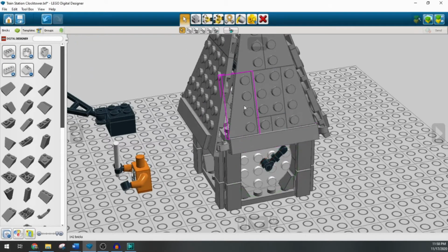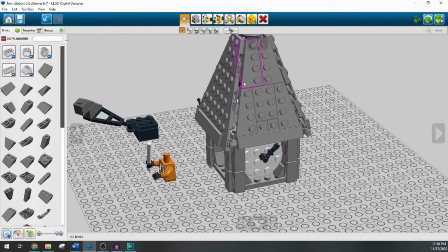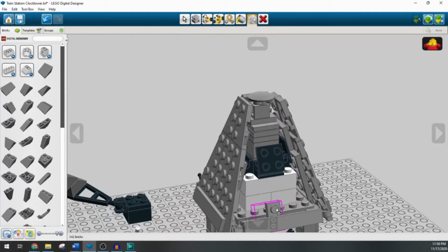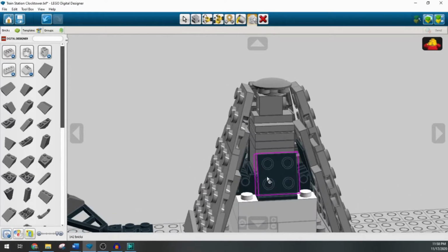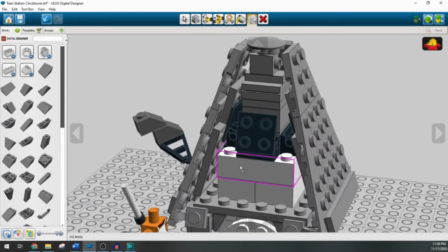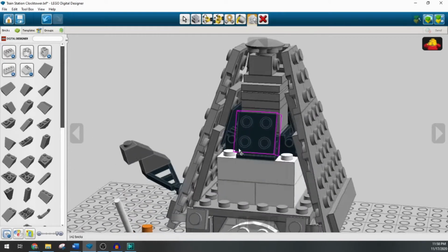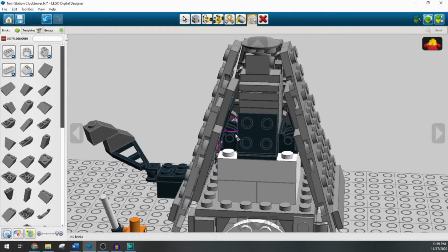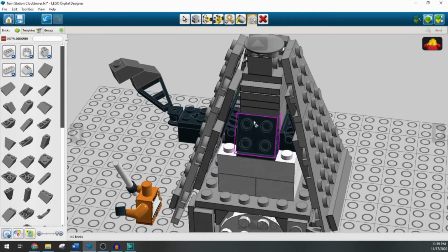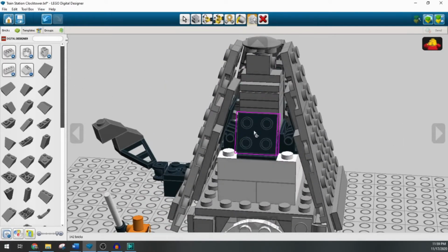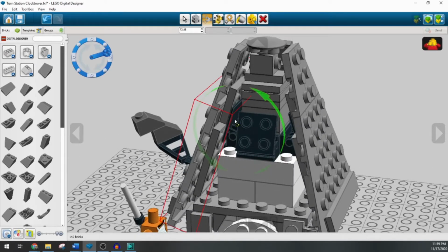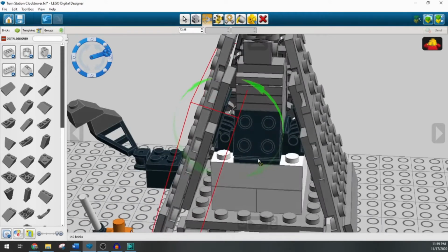But where the hinge tool was essential for building this was inside the roof assembly. So I'm going to hide one of these panels completely, open this up, and you can see in here the way I built this roof was using these hinge plates. And to actually get this angle correct, it was a trial and error kind of thing. So it's not going to work as well now because everything's kind of fixed in place. But what I did was I came in here with the hinge tool, and then I just click on this plate once it's in place there, and you can fine tune it with the bar. But it's actually locked in pretty tight right now.